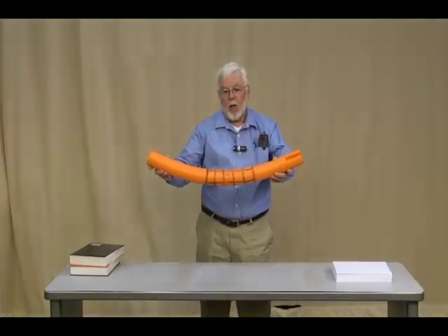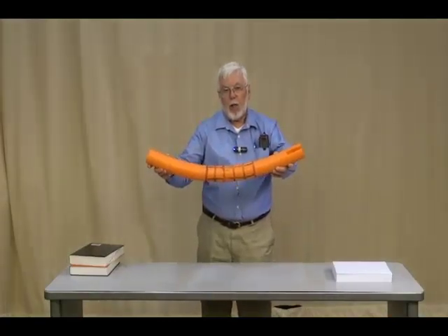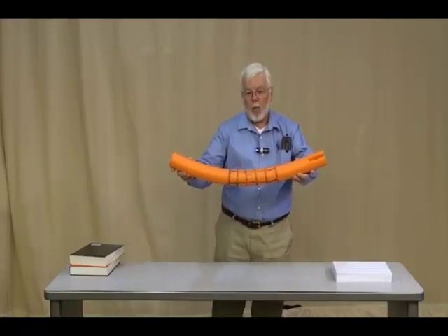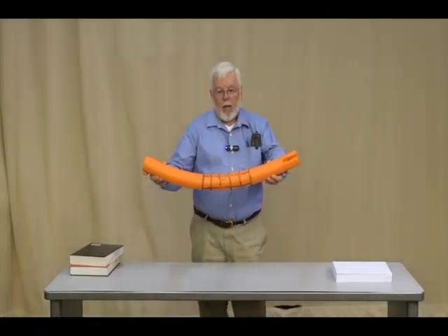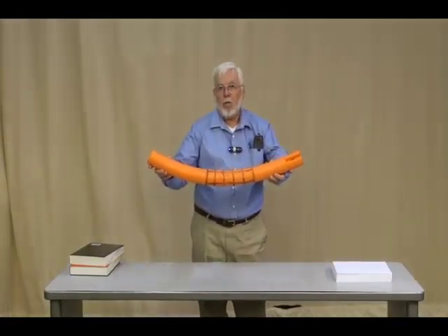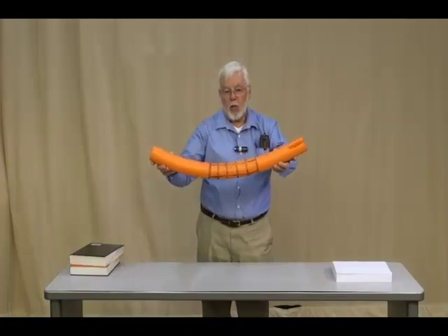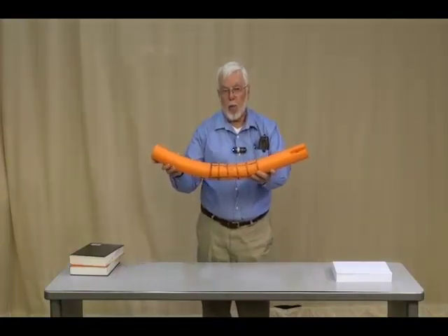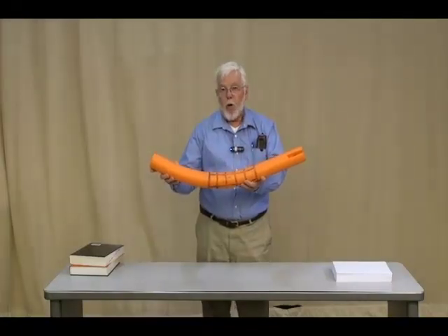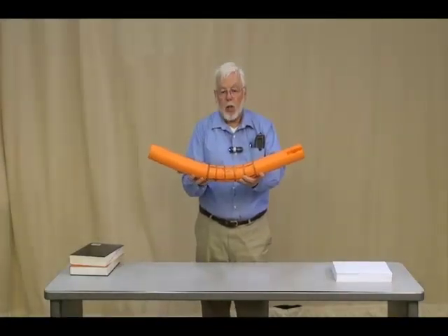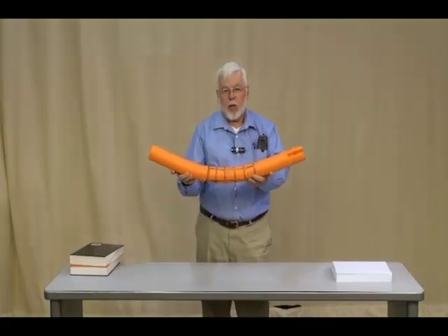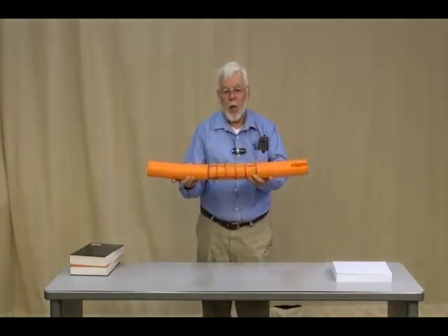So as a result of that, we have shear stresses being developed inside the beam, called transverse shear is the proper name. And these shear stresses are in essence between the layers of paper, which don't exist, I realize, in this beam. But if you imagine this is made of a bunch of layers, and the layers are effectively glued together, they're trying to separate, and in the process of trying to separate longitudinally in that direction, they are developing shear stresses one to the other.